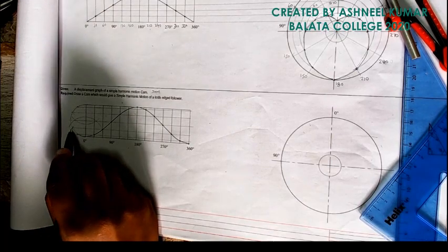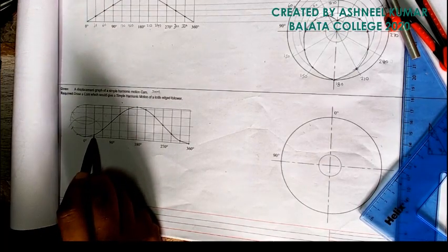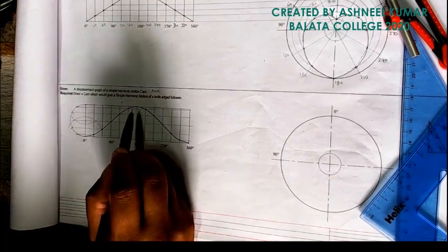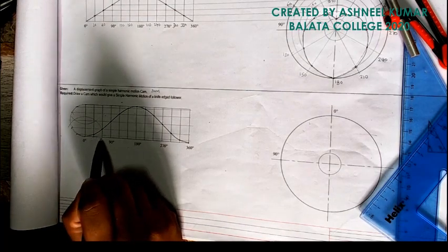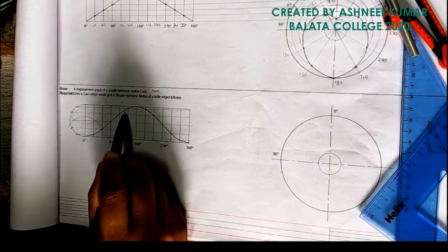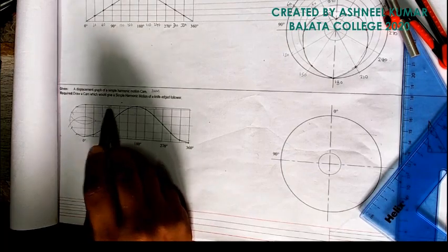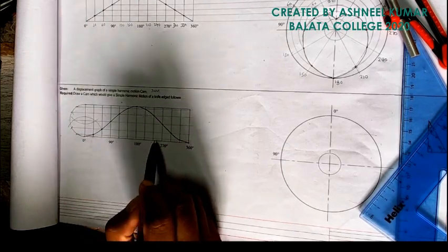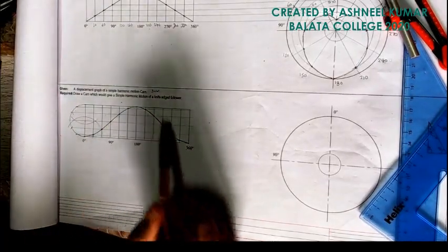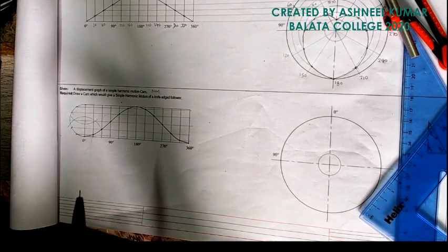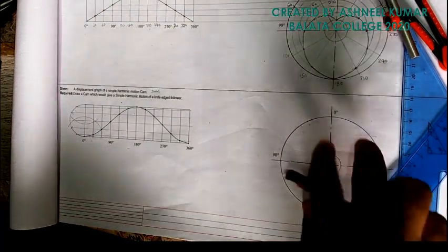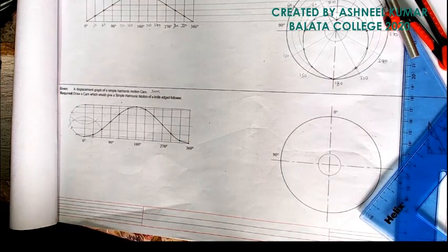Simple, you can label this as 30, 60, 90, then 30 there, this will be also 30, right? In this manner you can draw the simple harmonic motion, right? First point, first line, second line here, second line there, third line, you can follow like that. The last one will be right on top, then you come down again. So that's how you draw simple harmonic motion curve, which is not required here because you already have a curve. But in case the question asks you to draw a simple harmonic motion curve, then this is how you're going to do it.